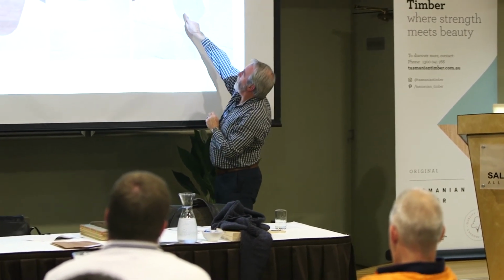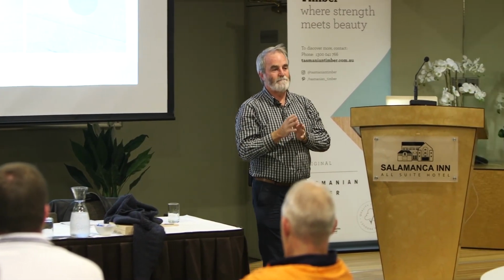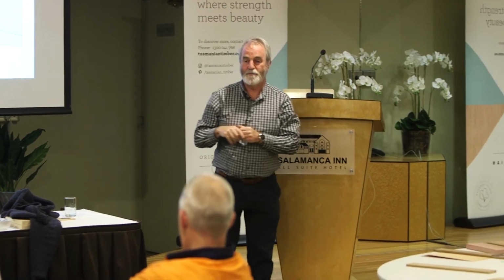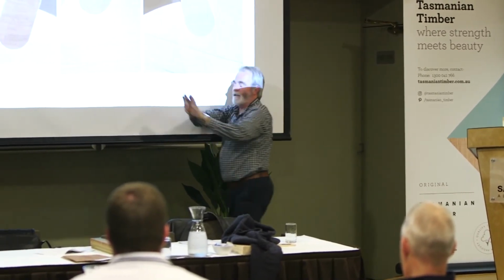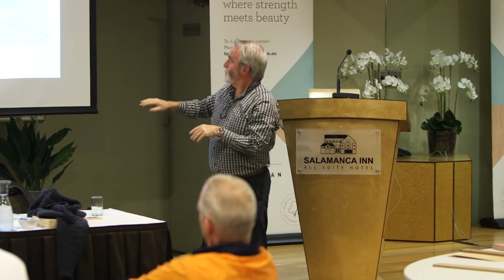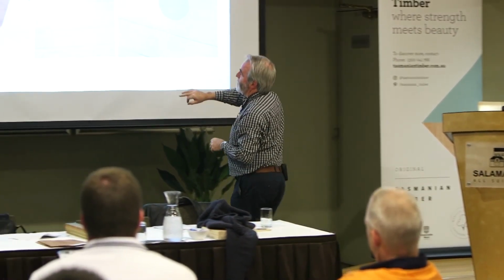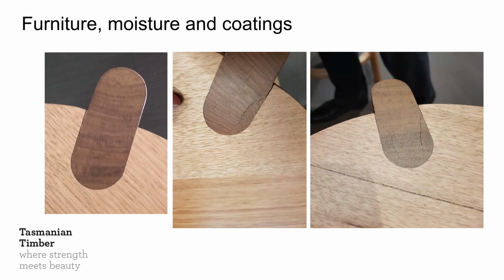However, they've been stuck to that bit, and this bit, wood across the grain, is much weaker than wood along the grain. So this is binding into there, and it's literally pulling the top apart, pulling that top of that board in and out. So here you can see it's adhered, and then you've got a space, and here you can see it's adhered and it's ripped that bit off, and here it's ripped that bit off.